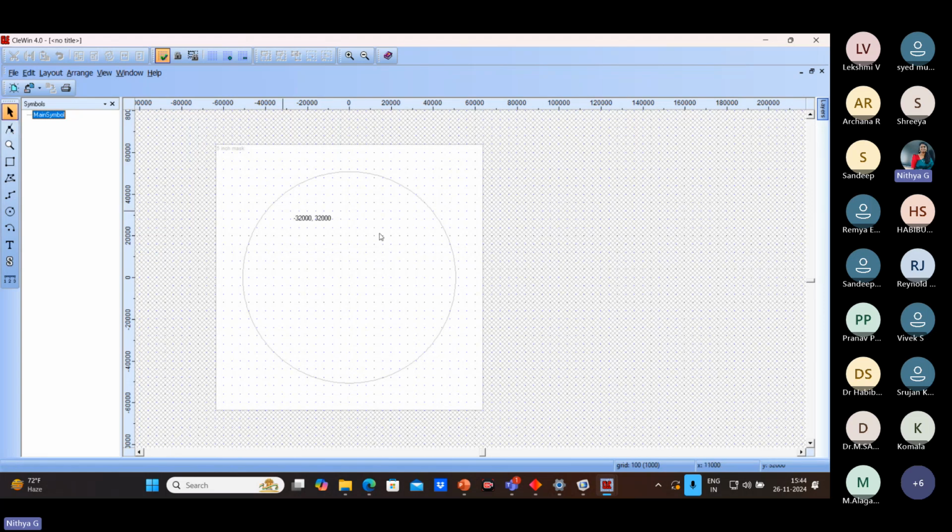Then I can select and edit that particular node. Okay. Then zoom option. Then if I have to create a rectangle or square, I have a direct option. It is similar to Paint. Okay. So this is rectangle. And if I want to create some polygons of random shape, I can use a polygon. If I want to use a wire for the routing purpose connection, then I can use a wire.